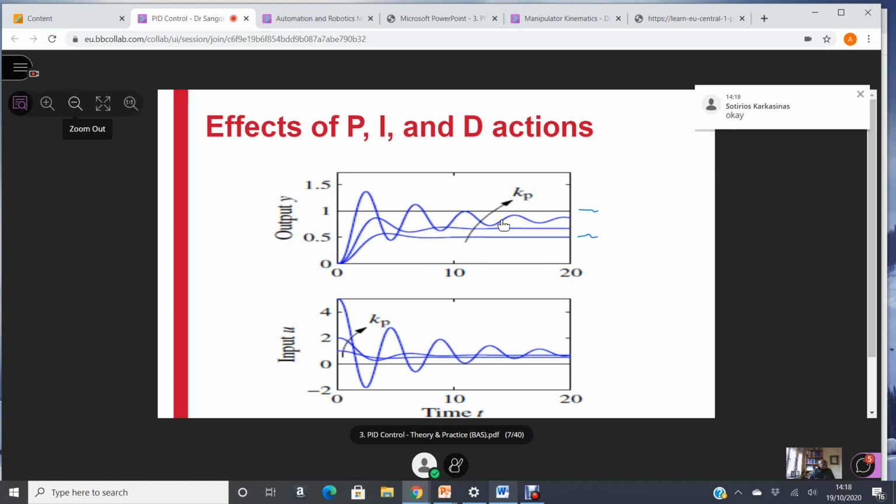So those are the two effects of proportional only control. One of them is very beneficial and it's what you're actually looking for. You can use the proportional gain to reduce the steady state error in the system. You take your KP high enough, you'll get a low enough steady state error. But it comes at the cost of risking the onset of instability in the response. Okay? So that's proportional only control.